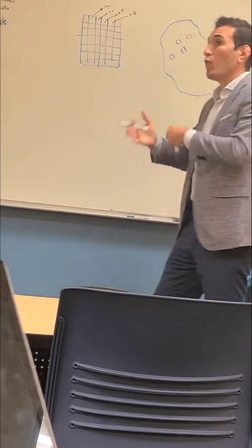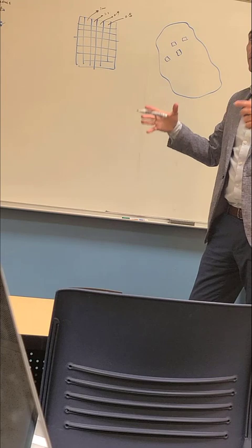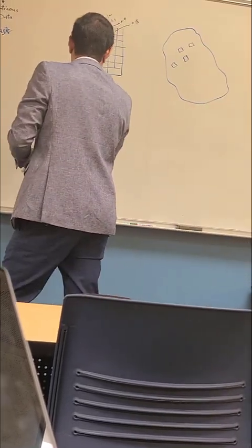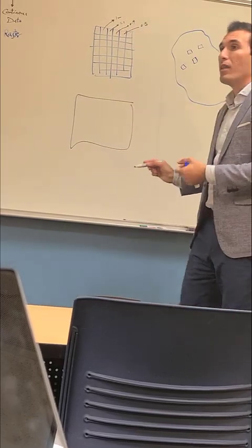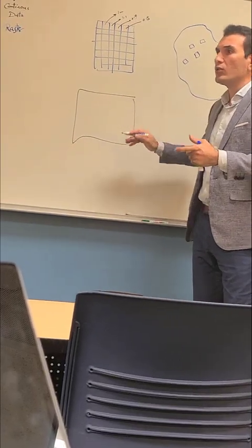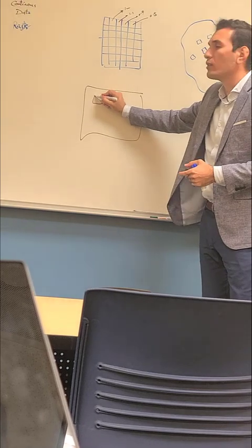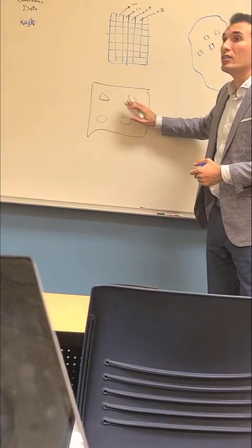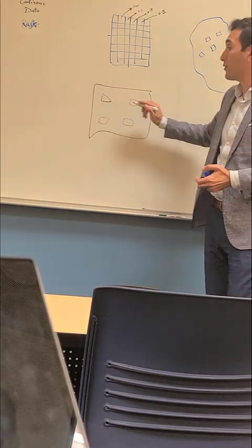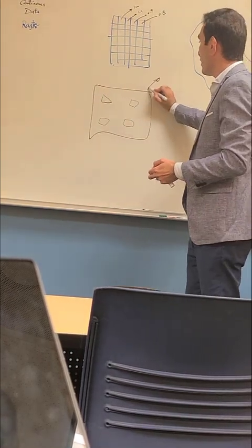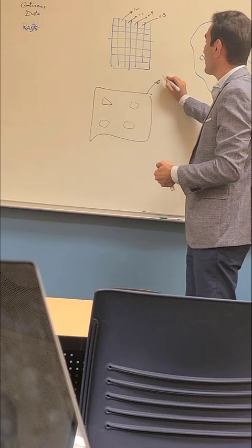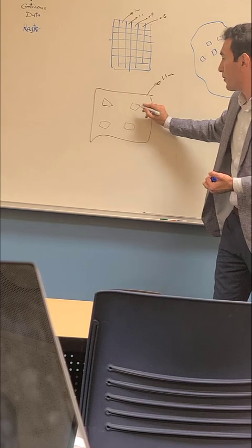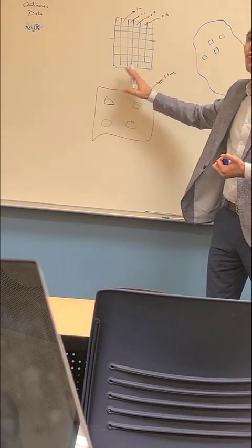So here is the role of the pixel size. If your pixel size is very, very big, let's assume it's 100 meter by 100 meter, I will have a problem. Why? If I'm looking at the flood depths and I have 100 meter by 100 meter, you can have 4 buildings in this area. And you will end up with all these buildings having the same flood depth, because this is my pixel size, and my pixel has only one value of the data, 1.1 meter. So when you extract the value of the flood depth at building 1, 2, 3, you will get the same.